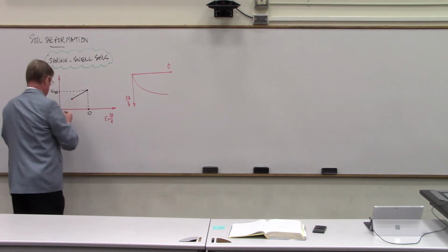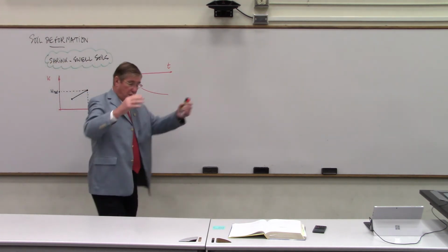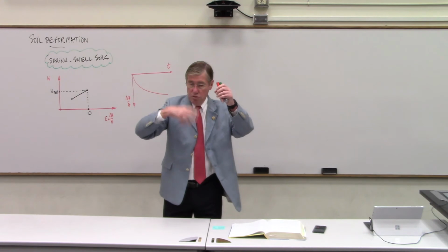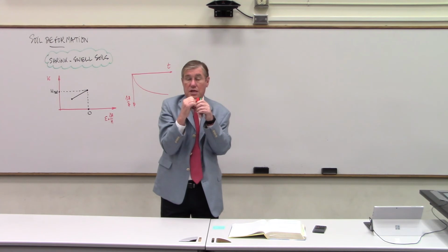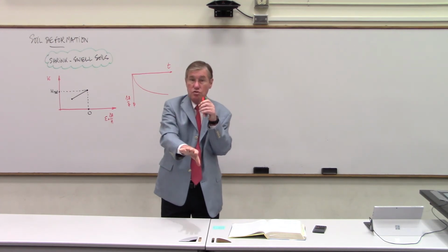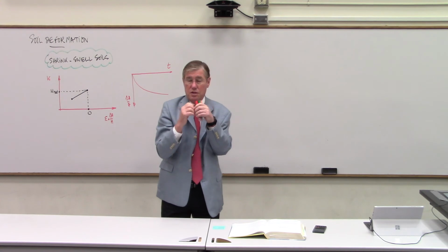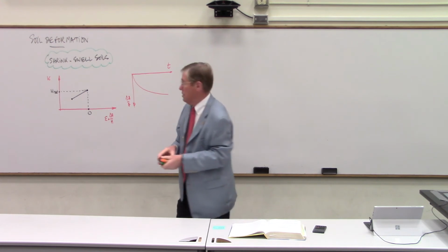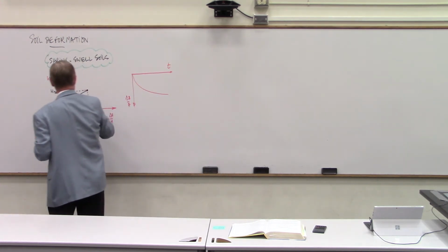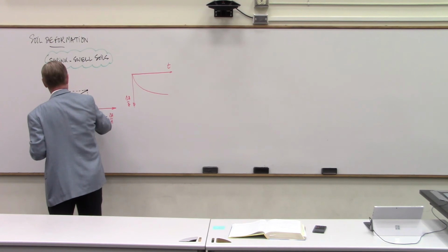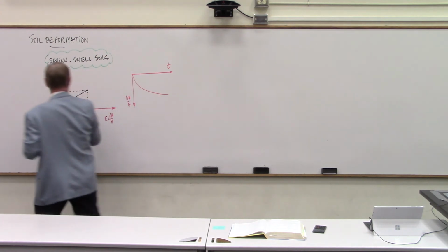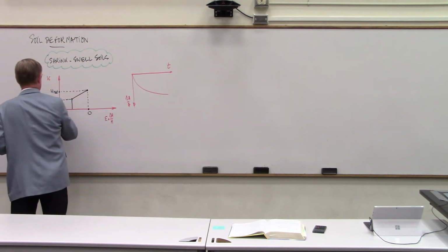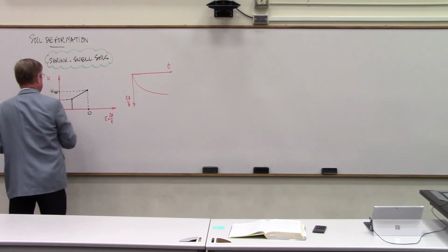And then at one point, you can imagine the particles are here, and you're losing water, losing water, losing water. Now the particles are touching each other, and they cannot shrink anymore. But you can still lose water from between the particles in the pores. So the shrinkage stops, but the water content continues to go down. So right here, and that's a bit of an idealistic behavior. It doesn't quite behave that way, but we'll put it straight down, okay? This we call the shrinkage limit, so WSH.